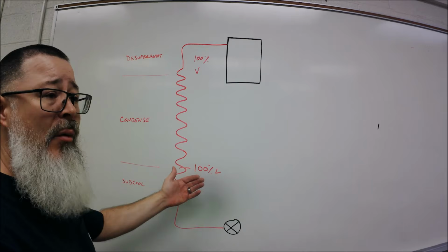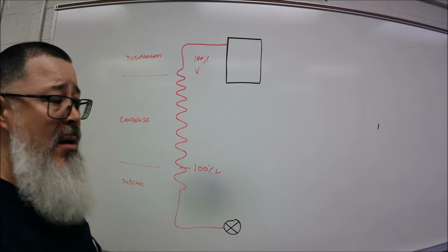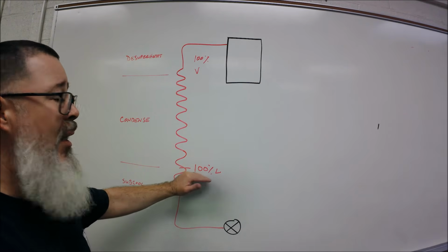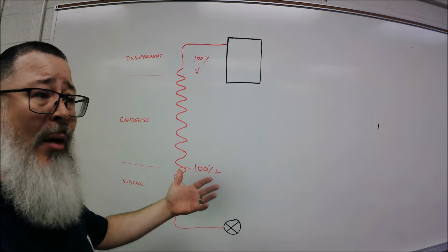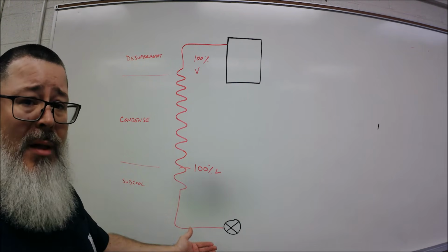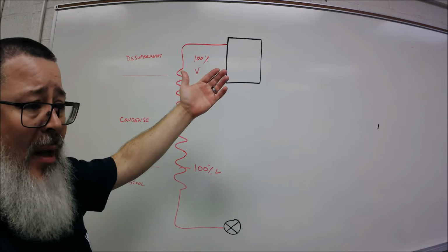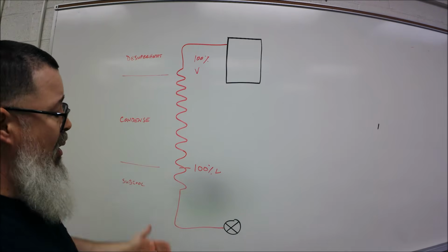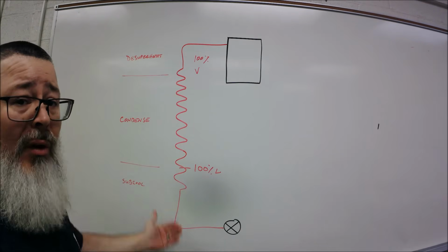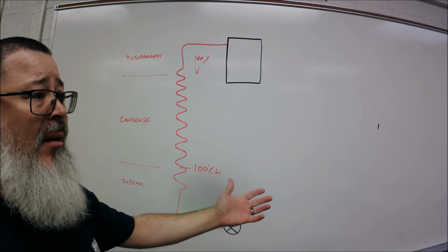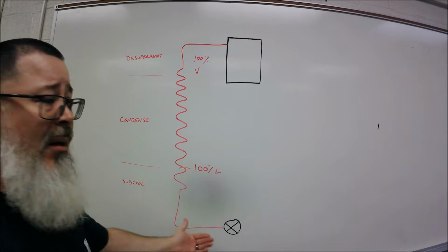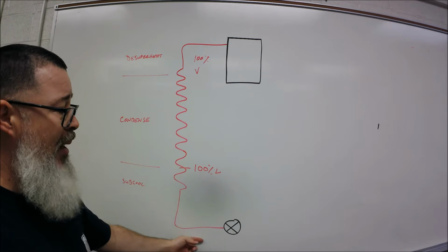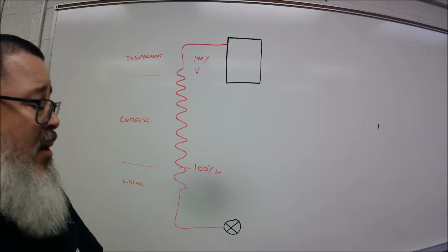We have to have liquid refrigerant going into our metering device so we can start that flashing process and the whole thing again. But we need to know we have liquid. And how do we do that? We're going to check our liquid line temperature, just like we check the vapor line temperature for superheat and compare it to our saturation point. We're going to check our liquid line at the end of the coil. Superheat's always at the end of the evaporator. Subcooling's always at the end of the condenser. We're going to check that liquid line temperature and reference it to our saturation point.